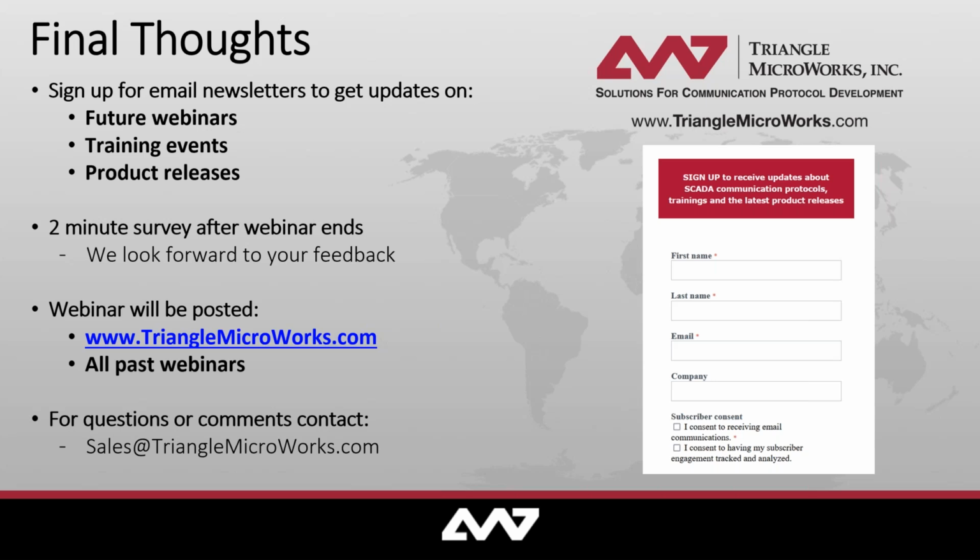Okay, great. Next question, I think this is going to be for you, Christoph. What is the purpose of the data type template section? Isn't this data already defined in the standard in the NSD files? The standard and NSD files define the data structure that exists in the standard, yes, but as we have learned today, not all the data objects and not all the data attributes of a common data class are mandatory.